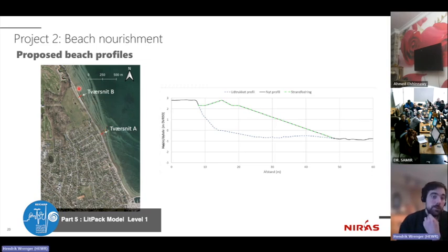So a much milder slope here at location B. And now we need to do some engineering judgment. It's not strictly uniform, the contour lines going to the south. How many different profiles do I now need to model where that will be relevant? And also not too many profiles, where all of a sudden our model results suggest some accuracy that's also not present. So here is where experience, discussion with colleagues, etc., comes in.